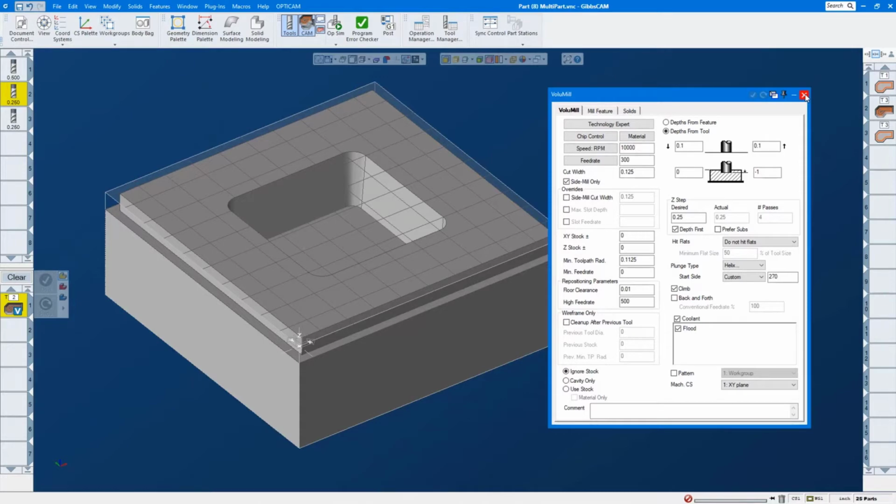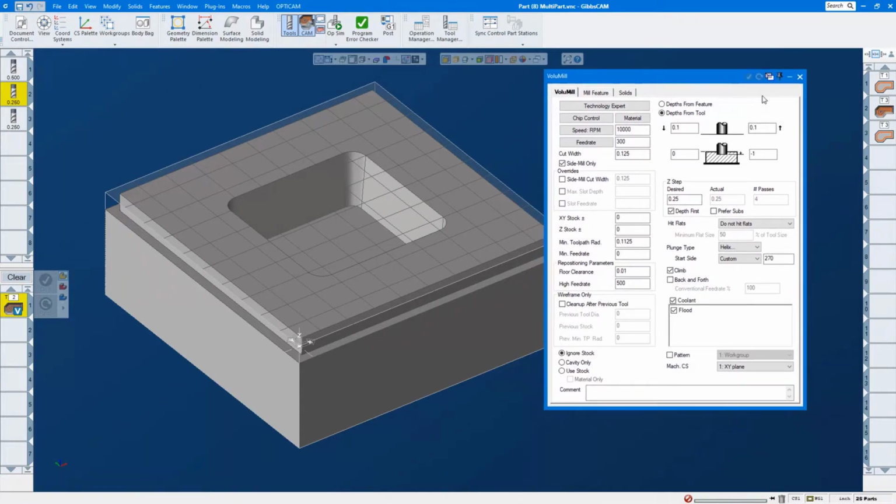Well, and if you pick the wrong drill size, apparently all bets are off. So it's really easy to think that VoluMill doesn't support pre-drill if you're following the same rules as the rest of the software, where you're just using a slightly bigger drill and dropping the tool into it. Basically, VoluMill needs to be able to helix through the hole that you've drilled freely. It can't just plunge down it. So it needs quite a bit more space. But if you're using a 1.5 inch drill for a 3/4 inch end mill, that's fine.